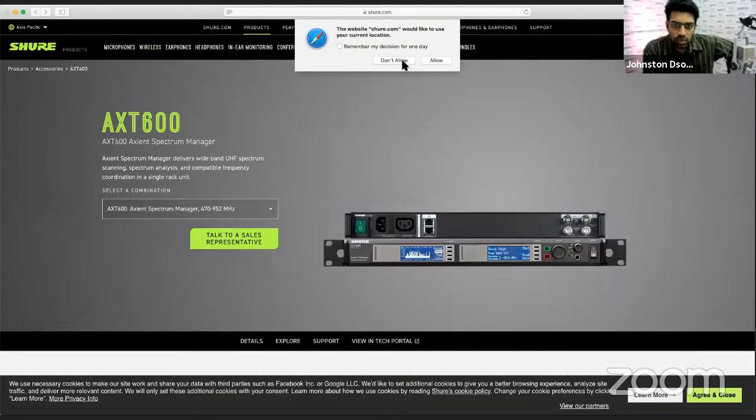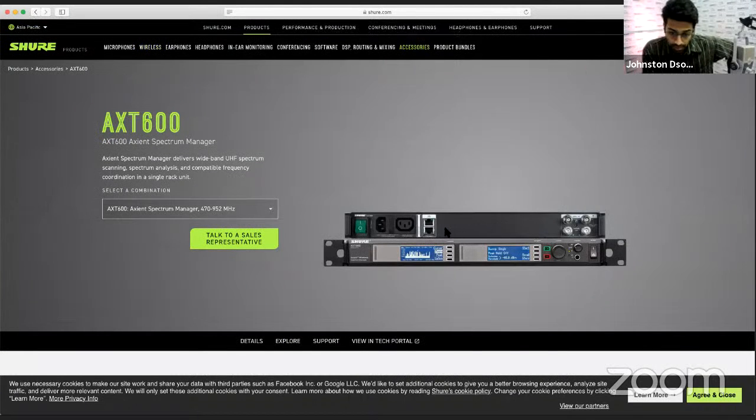So what it does is you can network this. The best thing about Shure is that each of these devices, especially in the Axient or even the QLX-D, all of them have 2 network ports, and they basically have a network switch inbuilt. Now, what is a network switch? If you take a router, there is one place where you connect to Ethernet, that is the modem, and the other places are just network switches. You get 4 network switches there. So you can do LAN connections through those. You can do that also on the Shure systems. Sennheisers unfortunately don't have those. You have to use an external network switch. But you can network all these devices together, and you can put them on a Wi-Fi network, and then you can monitor it using Wireless Workbench.